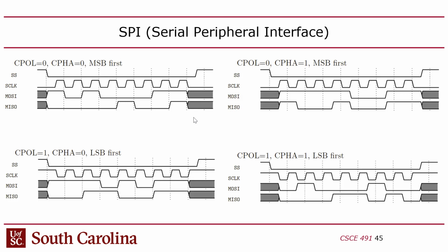That's when you have control over individual pins, GPIO pins, like basically just digital pins that you can set with software commands. In Arduino, it's just write pin, I think. Write pin, read pin, right? Then you could do this in software, in which case they call that bit banging, which is where you do software control. But generally, you'd have a hardware circuit that controls all this.